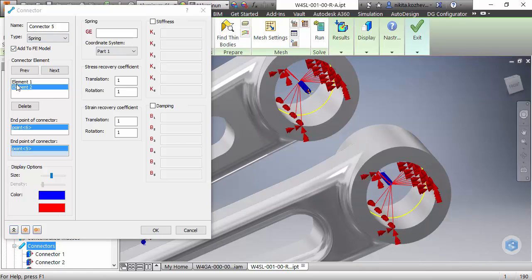So we can use the same properties for 2 spring elements. I would prefer to make it very rigid as well, just to constrain all degrees of freedom, or use it as a rigid connector between a single point and our rigid body element.